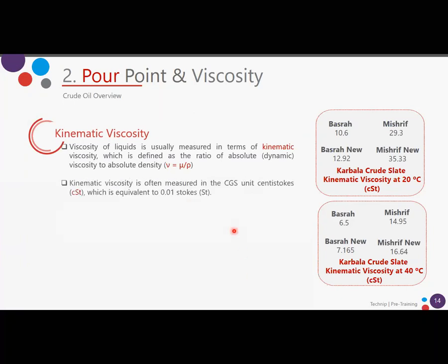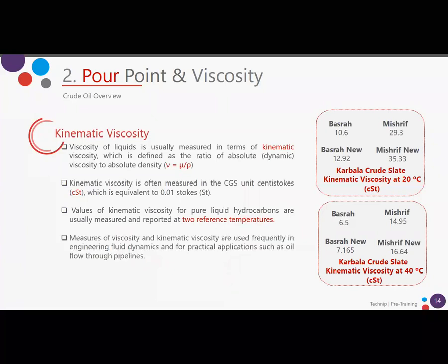Often the unit used for the kinematic viscosity is the centistoke. Usually, the values of the kinematic viscosity are reported at 2 reference temperatures. This measure of viscosity and kinematic viscosity are used frequently in engineering, fluid dynamics, and for practical applications.